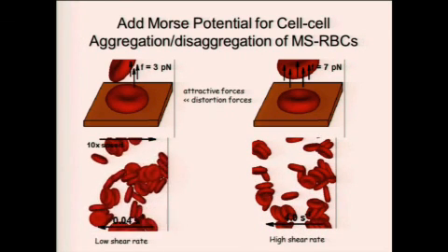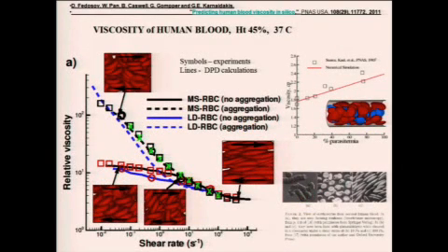So what do we do with that? We measure the viscosity in a uniform shear flow, Couette flow. That's the only way you can think about viscosity of particulates like blood, because the concentration remains uniform. So what do we have here? We have two curves. One of them is whole blood, and it rises as the shear rate, which is on the horizontal axis here, in reciprocal seconds, becomes small. The relative viscosity is the viscosity divided by the viscosity of the plasma. Plasma viscosity varies by up to 15%, so that tends to normalize things.